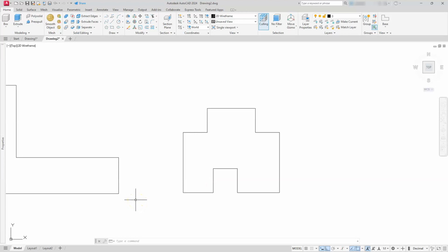The last shape that I'm going to need to create is going to be that square that's located right under here. I'm just going to use a rectangle command, which is located here. I'm going to click this endpoint, and I'm going to go down to this endpoint. Alright? That's another kind of important feature that you must learn, is that you can't have shared lines. So I had to create an all new square here, and I'll go ahead and move that for you just so you can see that it is indeed one shape. You see all of these lines were shared, but anytime I'm creating a 3-dimensional shape, I can't really share that, if that makes any sense.